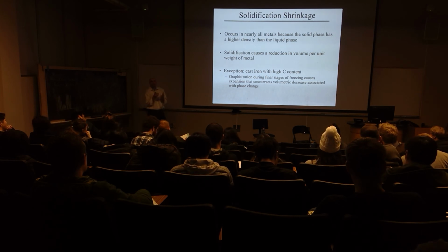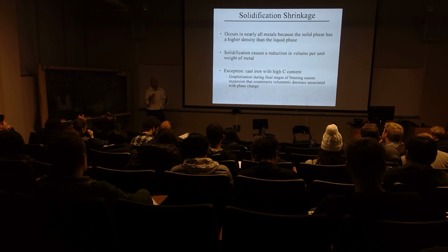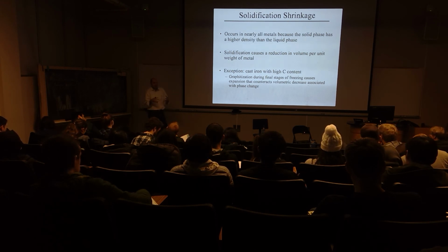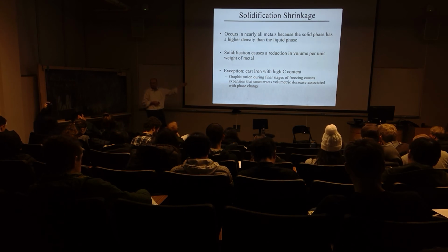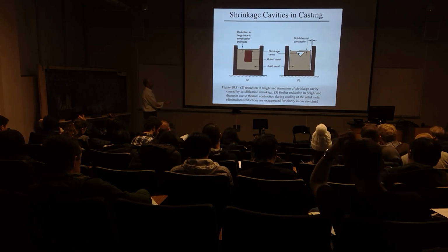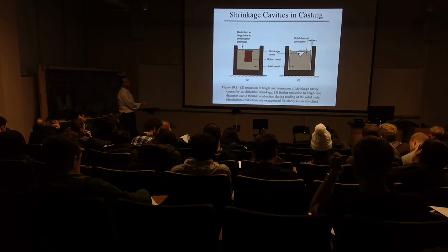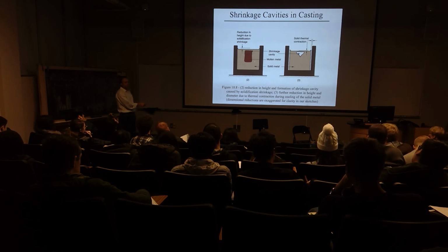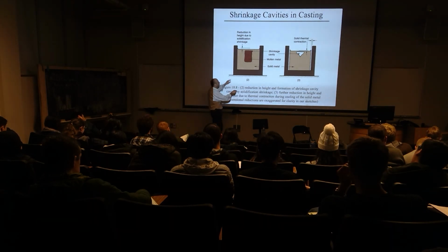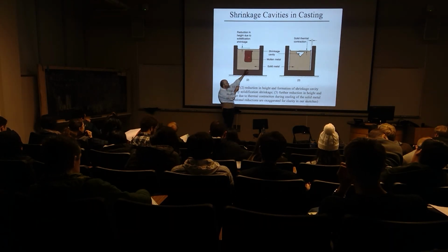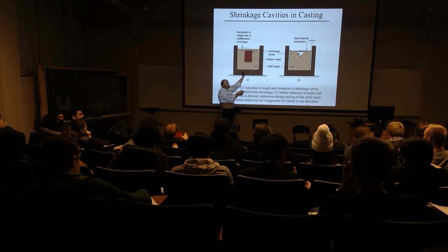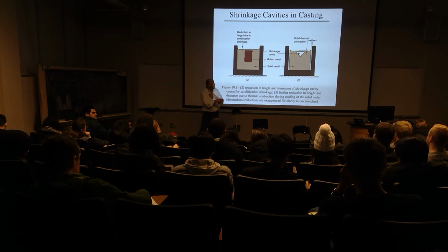And then that becomes important to being able to use a mold that doesn't constrain that expansion, because it will cause cracking if it has enough internal stress at the hot temperatures in which it's undergoing this solidification process, right? So what can that cause? So the liquid metal, which we were worried about before, can enable segregation. That will also be locations that we can expect to see voids. And the reason is because the outsides of the mold will always be skinned, and the metal will fall to the center, and if these skins develop that restrict the ability for metal to fill the mold, it'll actually shut off the flow of metal and you get these voids.